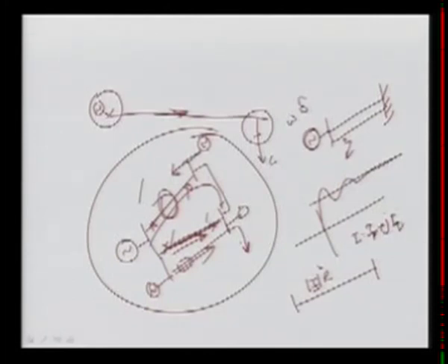Now if this is less, then you can go for more real power current, and then you can transfer more real power. So if you are having this, then this will be reduced, because I square is the limiting value of the transmission line, because I square R is the loss, and it is the limiting value, that is the thermal limit. So with the help of this, if we can control it, we can minimize this and go for more real power.